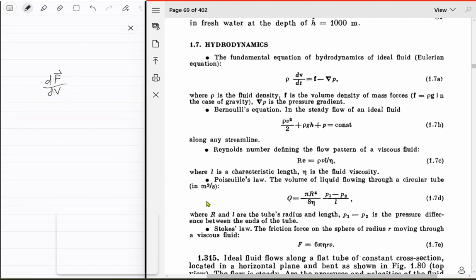Okay, and for most cases where you don't have any crazy forces acting on the liquid, your small f vector will be the same thing as rho g, because the df vector acting on our dV volume is just its gravitation, right? Which is rho dV times g, g vector actually. So yeah, this small f vector will just be rho g. That makes sense.